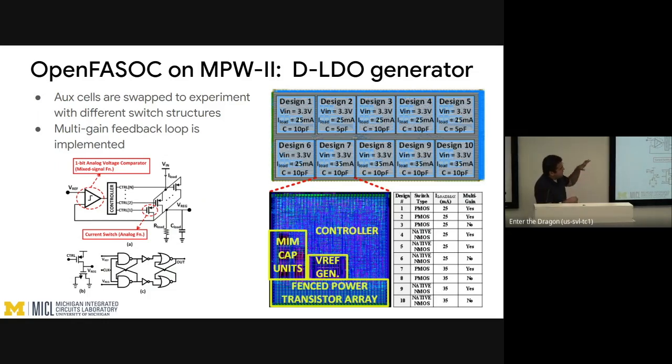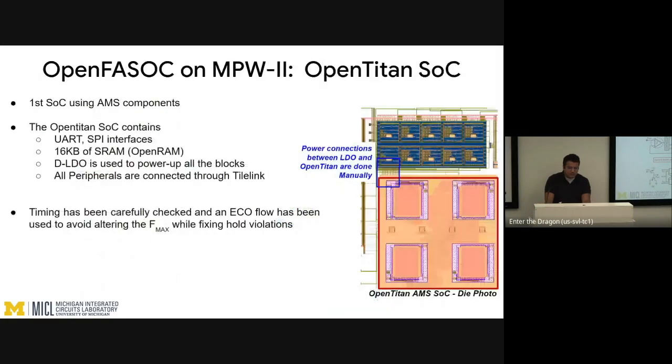We used a standard cell-based comparator, but we used a StrongARM latch comparator as well. I think that's very useful because you can generate thousands or hundreds of thousands of these LDOs. We just generated 10. But you could do that and simulate them without taping them out and see which one is great. So I think that's very useful. All right, so this is the top diagram.